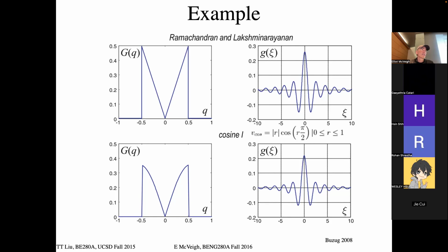We've got noise, right? So the noise basically has a very broad bandwidth. And so you will amplify noise incredibly by multiplying by this filter. You're saying, oh, all my points up here are being weighted very heavily in my image reconstruction. They're principally noise, right? So you're just going to get a bunch of noise on top of your image. And so a number of attempts have been made to make this filter behave in a more user-friendly fashion, so you don't have to look through a lot of noise, right?